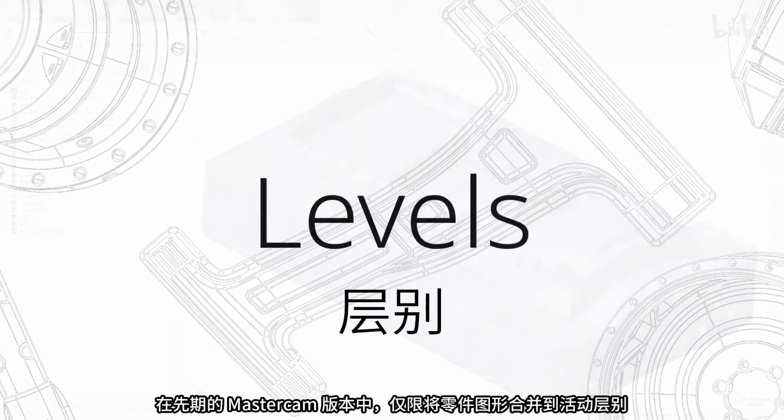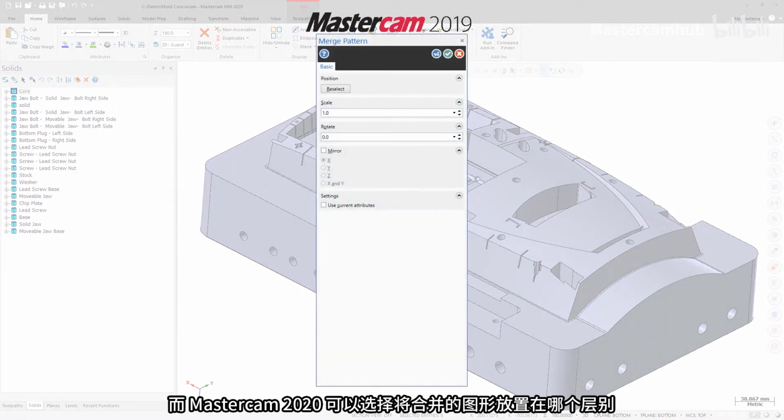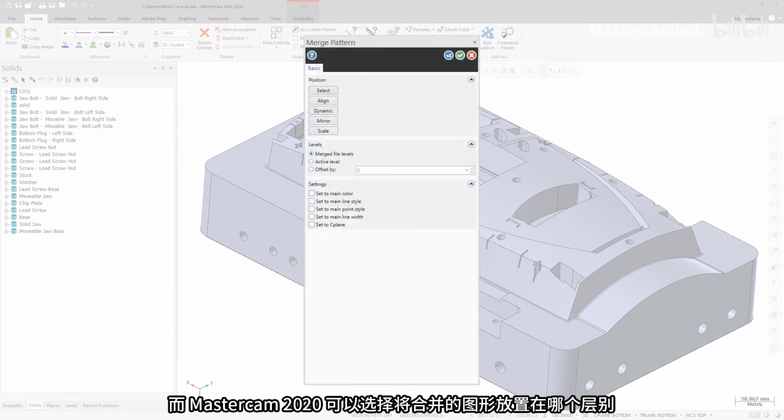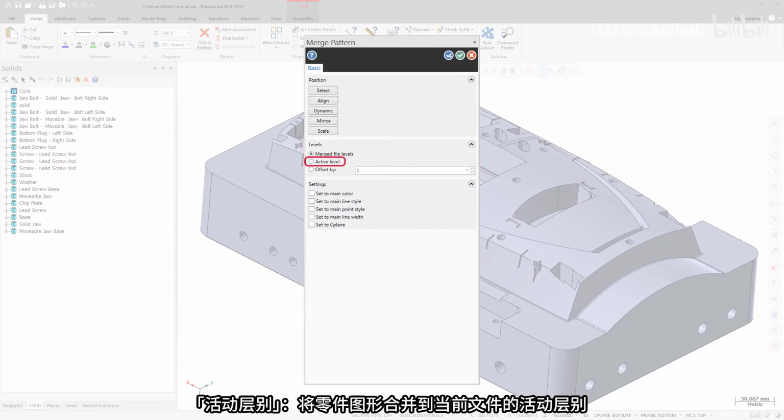In previous versions of Mastercam, you were limited to merging part geometry into the active level. For Mastercam 2020, you can choose on which level merged geometry will be placed. The new Levels group on the Merge Pattern function panel has three options. Active Level merges the part geometry into the current file's active level. Merged File Levels places the merged part geometry on its original levels.